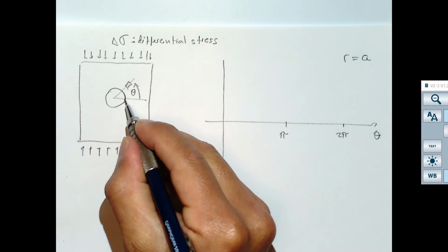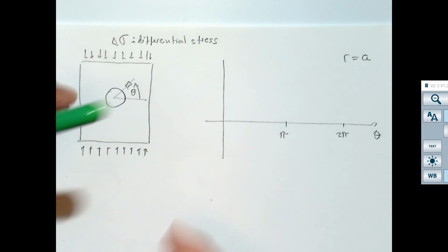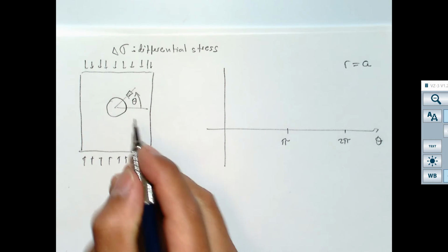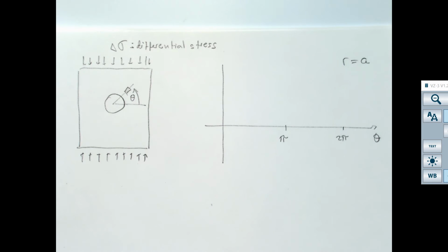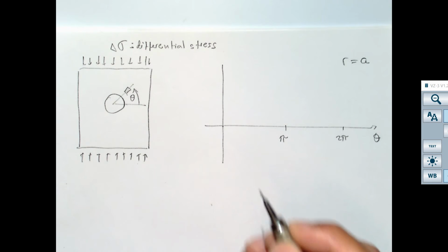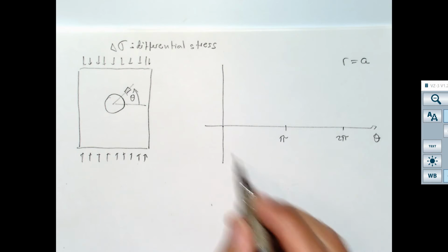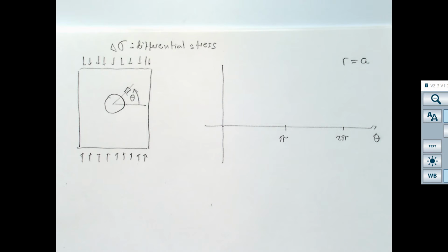Here, compression, right? Because we're pushing in this direction, and therefore the stress have to go around the wellbore and will amplify. The compression will amplify in here. So very likely at 0, this stress is going to be a compression.